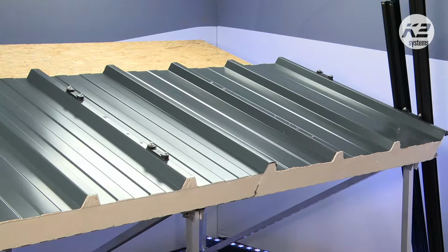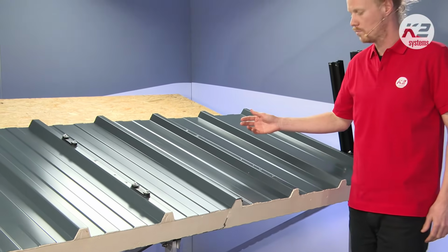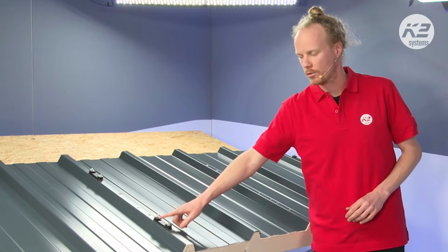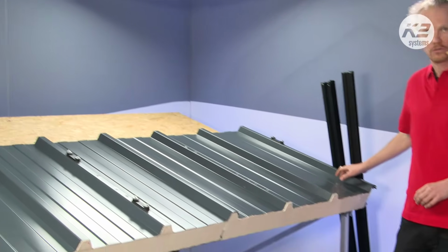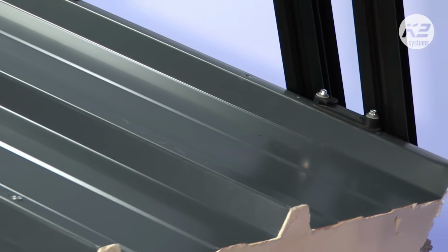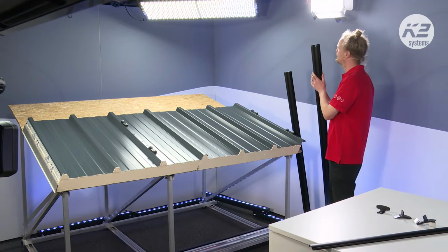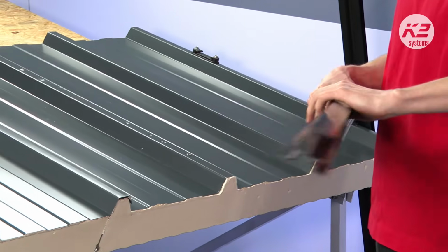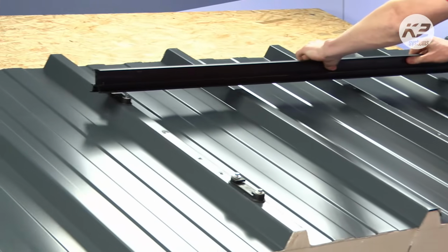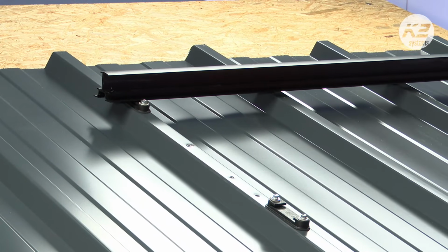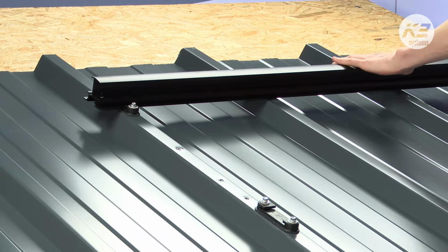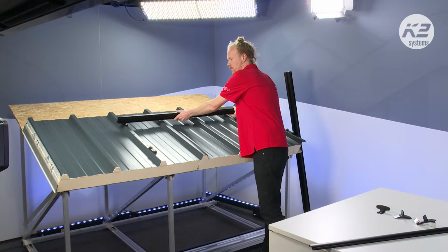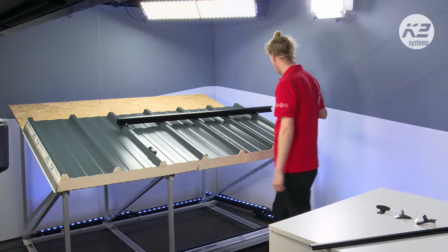But what we're going to do generally, and this first part is the same as what we would do with a trapezoidal roofing and basic rail, is we're going to put our two outside basic clips onto the roof. And then we take our rail, and I mentioned before that it's asymmetric, so our longer side is always at the bottom, and our installation just goes up into the top, as we showed before, and comes down, and you can pull it down. All right? And so we just do that, we've done it on the top rail, and we can do it on the second rail.